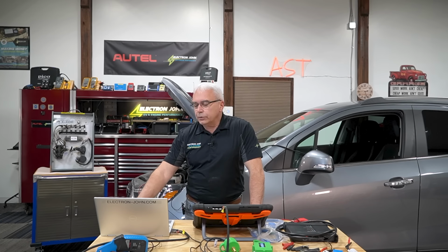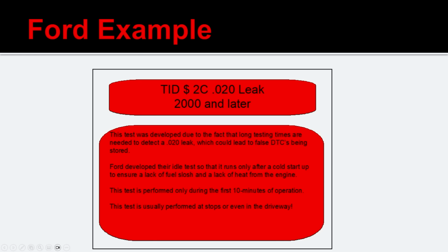So again, if I go to another slide here and kept talking about it, I would walk you through the most logical types of tests. But if I had a generic code, for instance a P0440 for an EVAP related code, mode 6 could be very beneficial. If I thought it was a 440, we'll use backyard mechanic mentality right here, people say, well, let's put a gas cap on it, right? Well, is it going to fix it, right? Now, you would know that if you understood how to interpret the mode 6 data.